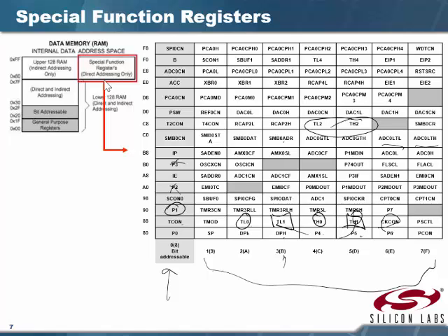Like this one here, AMX. That's analog mux 0, and then we've got 3 different control registers. Without referring back to the data sheet, I'm not going to tell you what those mean because I'll probably get it wrong. This 300-page document that I'm not scaring you with goes through each one of these registers in great detail and how to program them for certain functions.